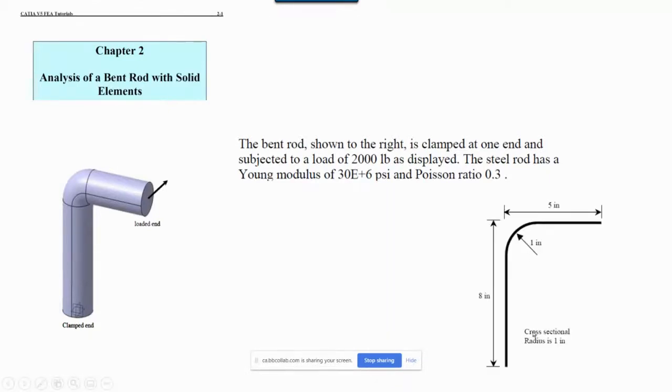And the way we're going to create this geometry is we create a circle at the bottom of this, and then a path, and then a rib, R-I-B. CATIA calls it ribbing. In other software, it may be called extrusion or something like that. But CATIA calls it rib.